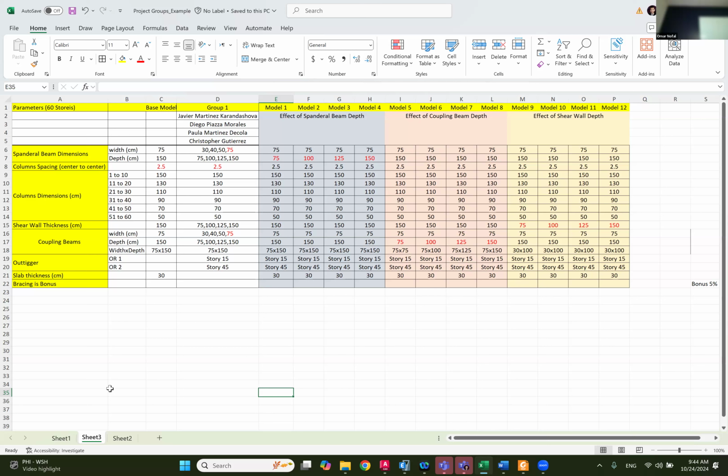All right, you build the models. That's step number 1. We build the models without anything, okay? And then we apply, but for the base model, once you build the geometry, you assign the earthquake weight. I'm gonna tell you how to assign the earthquake weight, so that you don't have to define the earthquake weight for each model. Once you save as, the model is gonna be saved with the loads on it. So you don't have to define the load again, all right? So that's one note to be said right now.